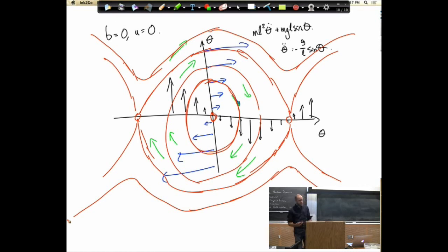Okay, so this is the phase portrait of the nonlinear, undamped, no input pendulum. So if I started here, for instance, which would be like this, then I drop it, and if it's undamped, it'll just go like this forever. And that is equivalent to going around. It's always going to go clockwise in these plots. It's going to go around in these circles, yeah?